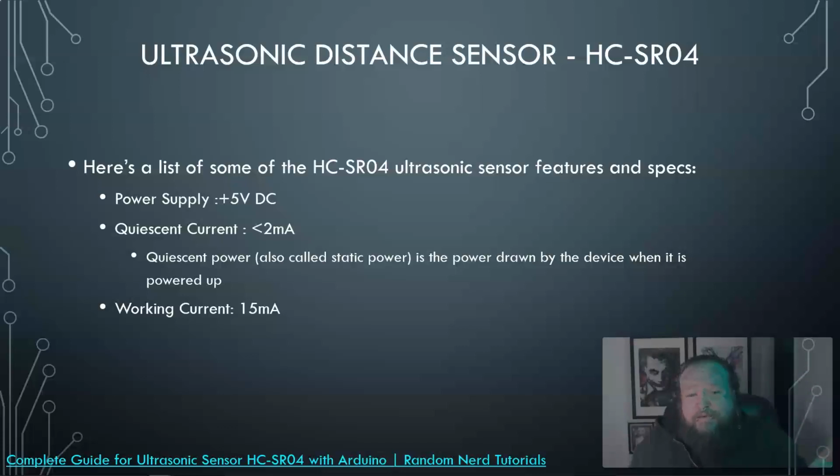But we're starting basic, and you should at least take into account how much it needs. Because remember, if something's not working right in your project, this is one of the things you could take into account. How many things do I have connected? How much current does each need? And is this overtaxing the actual device, which is then causing issues?